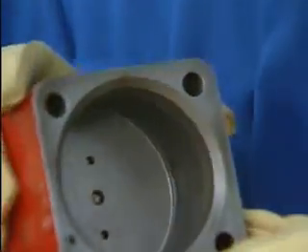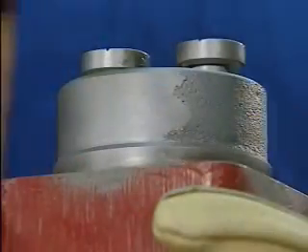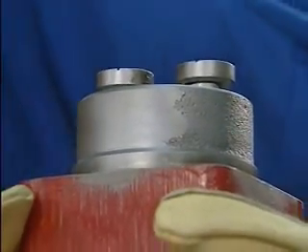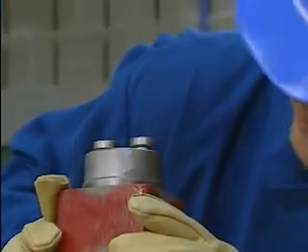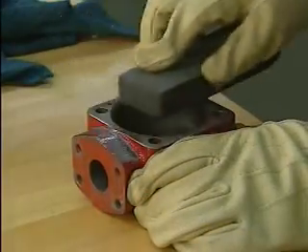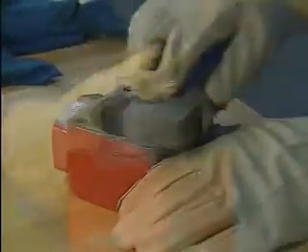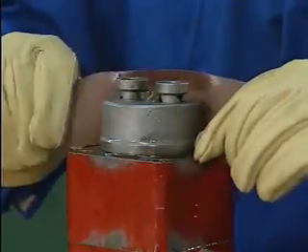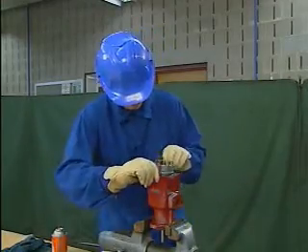Once they're clean, the mechanic checks the sleeve and sealing surfaces for any signs of damage. It's very important that the sealing surfaces be in the best condition possible. Even small burrs or sharp edges can cut an O-ring and cause it to leak. Burrs and sharp edges on the flange face can be removed by stoning the surface. Imperfections on other parts of the flange, such as the sleeve, can also be removed by polishing the surfaces with grit paper.